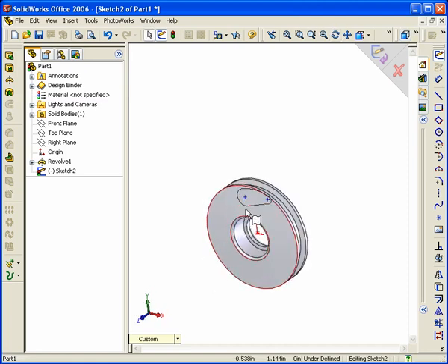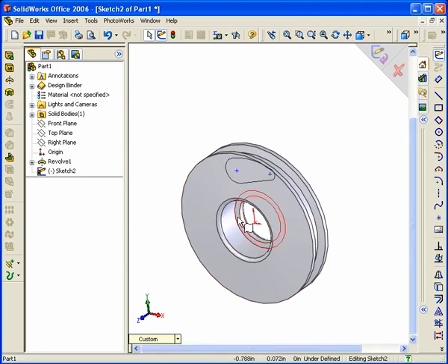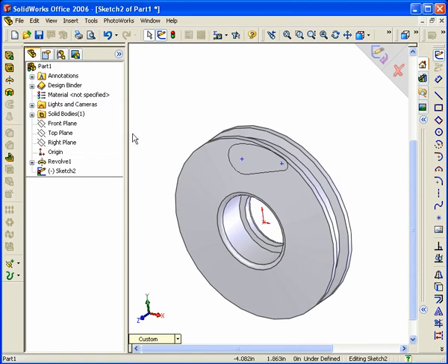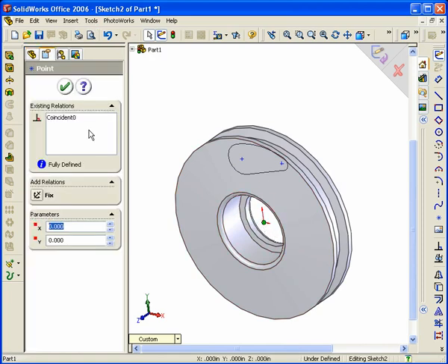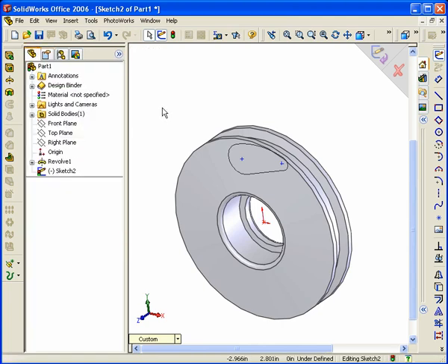Now if you want to continue to add the constraints and things like that that we did earlier, that's fine. For review, we'll do that one last time here. Again, remember we have to remove any constraints, so we select that center point, find the coincident relation, and delete it. Hit the delete key on the keyboard, or you could right click in that box and hit delete all.